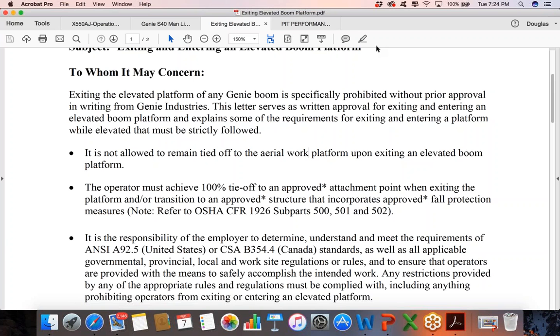Okay. Also, headgear, right? We have to make sure that if we wear any type of headgear, are we hard cap welding or soft cap welding? If we're soft cap welding, we want to make sure that cap is made out of some type of material like cotton or preferably wool, right? Same thing to have less of a risk of a hazard. There are very few locations now that allow welders to weld with a soft cap, but if a soft cap is used, you have to make sure that employee, when they leave that area, or if there's an overhead hazard, puts that hard hat back on.